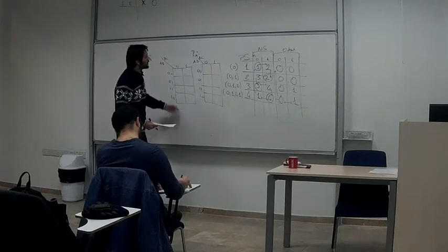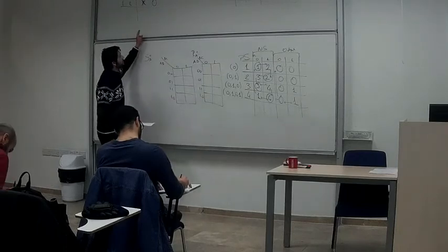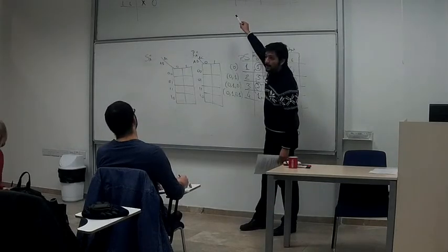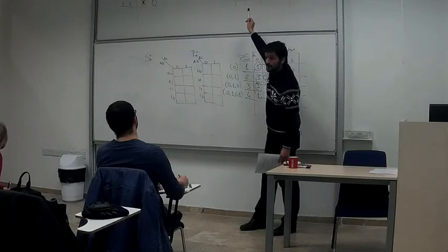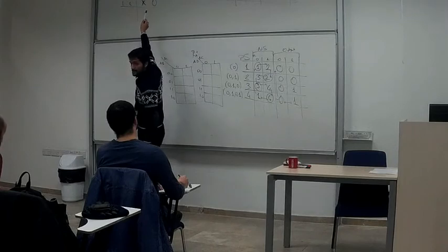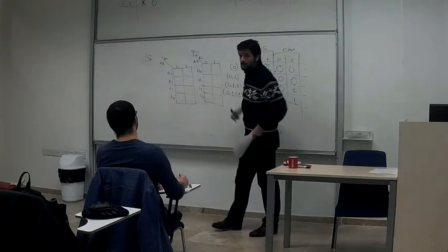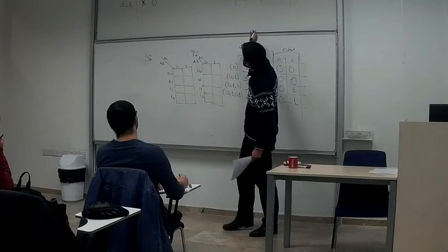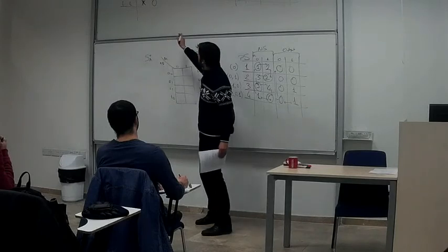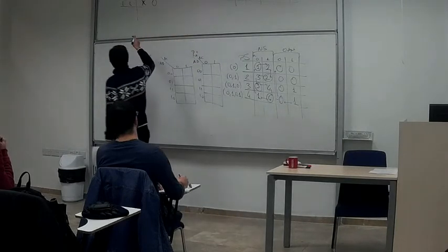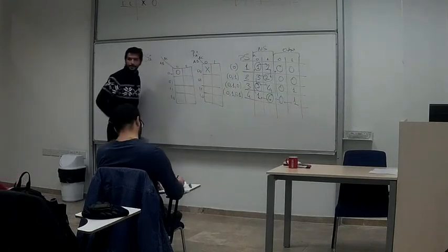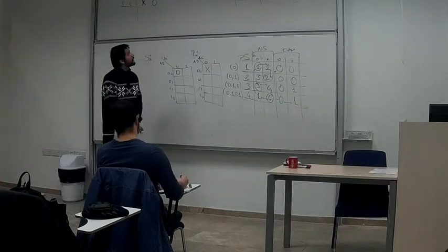For A, how do I do that? Using this SR. So for the first one, we had an A as 0, and the next thing with RC 0, it's 0, right? Whenever it's 0, 0, we had an SR as 0 and X. So we don't map those zeros, but using that information, we map whatever it corresponds to in the SR latch, okay? This is important. So for S, I'm going to put a 0, and for R, I'm going to put an X. So it's 0 and X.